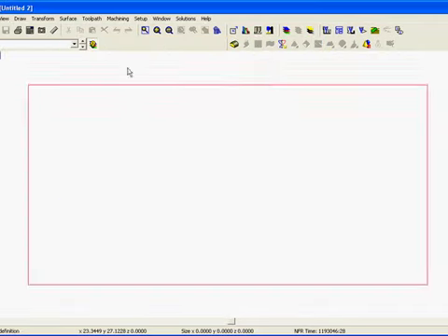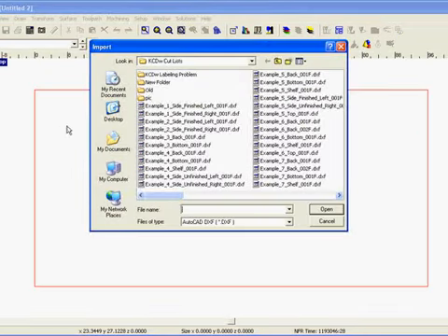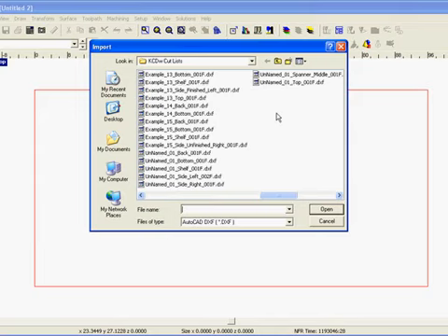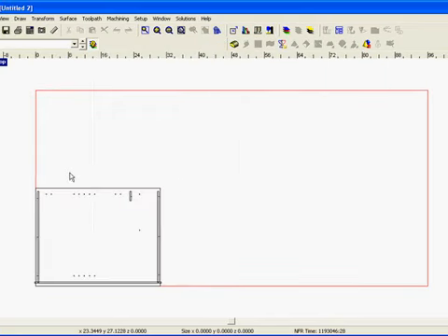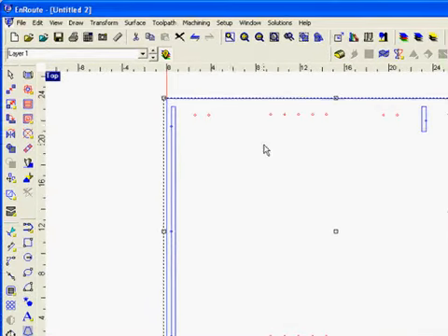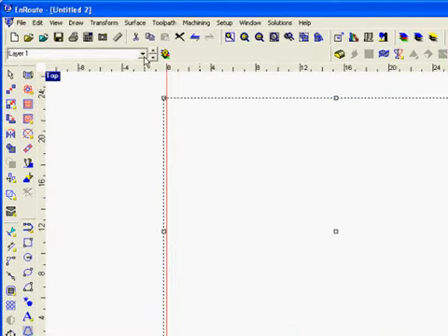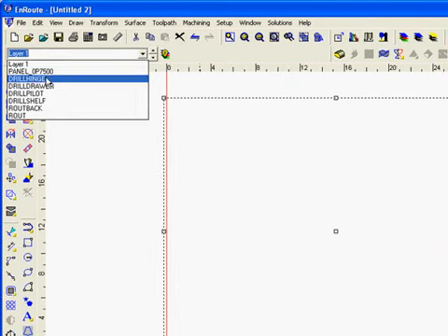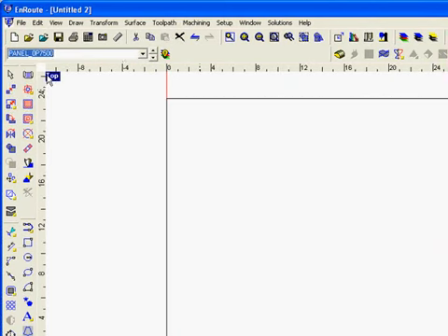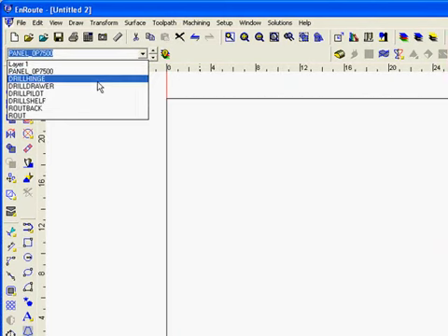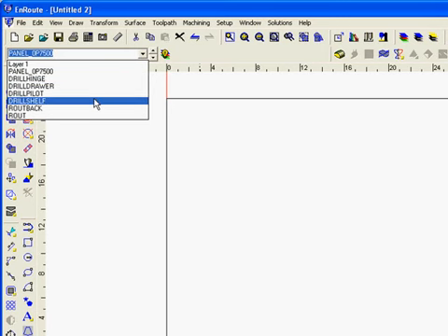We're just going to open up a default plate size, and we'll import a DXF file. And this is one of the DXF files from the job we ran in the overview. As you can see, this one DXF file was a whole complete part, and there are different layers here. We have a layer that determines the cutout, and then we have some drill layers for drill hinges, drill drawers, drill pilot, drill shelves. These may or may not be going to the same depth, except in the case of drill pilot, it's always going through, so definitely not this one.